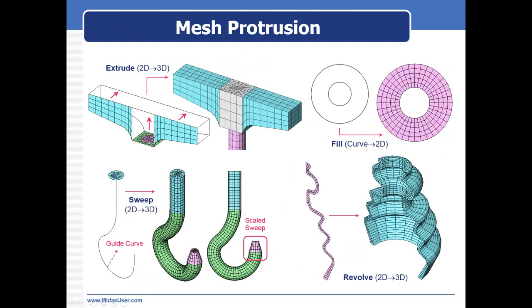Next is mesh protrusion. FEA also supports CAD-based features, not only for geometry but for meshing too. So for profiles like these, we don't need to generate the geometry actually. We can just sweep the mesh along this curve to get this profile. Likewise, we have revolve, fill, extrude.